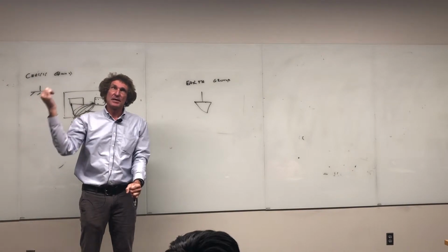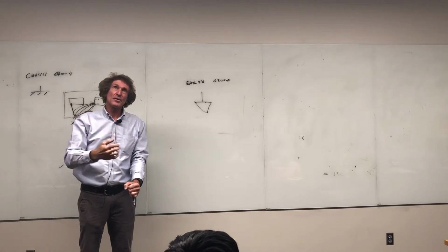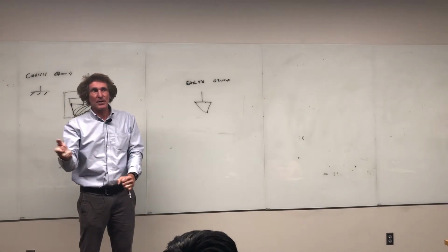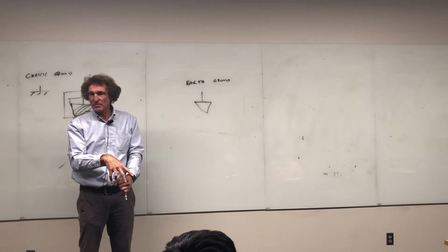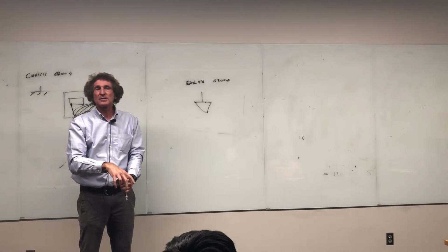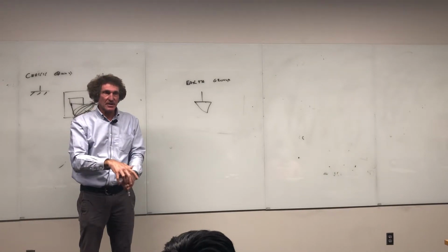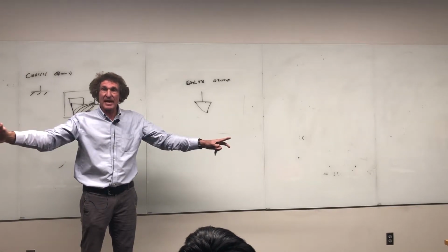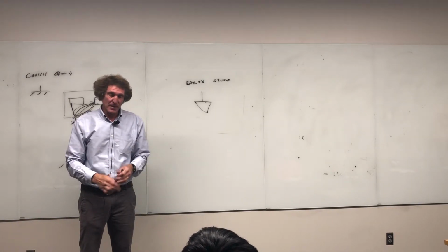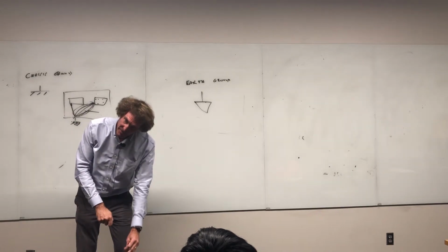Now, that grounding rod is supposed to be pounded into the ground, and I think what they tell you to do is put water, and I don't know if they allow copper sulfate or what they allow around it. They put it on there because copper sulfate's a very good conductor. It'll make this thing have a very low resistance to the outside world, the earth around it. And you pound it in, get it down there.